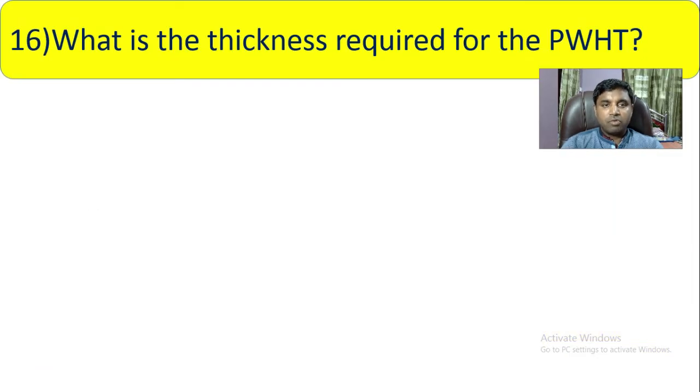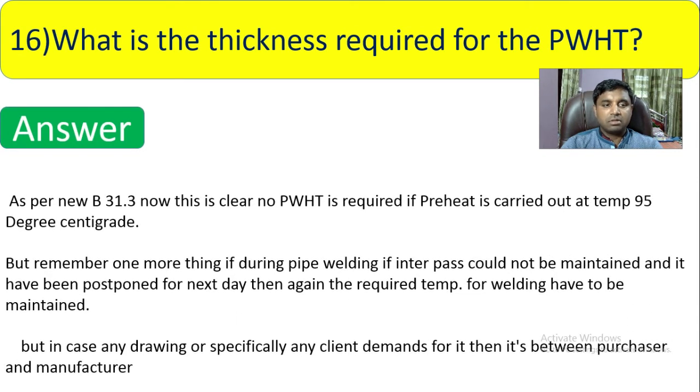Question number 16. What is the thickness required for the PWHT? This is a very important question. Answer is, as per B31.3, there is no clear requirement of PWHT if preheat is carried out at a temperature of 95 degrees centigrade. Definitely there is no need of PWHT. It is saying in B31.3.